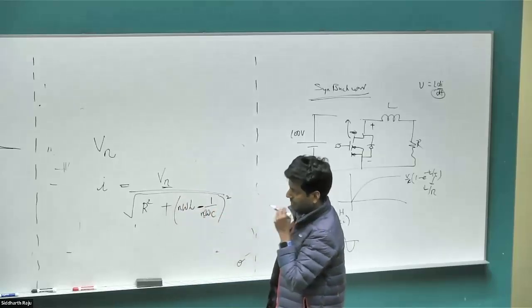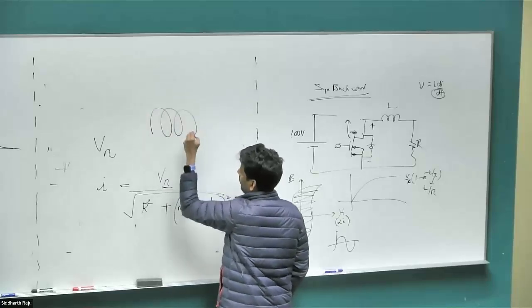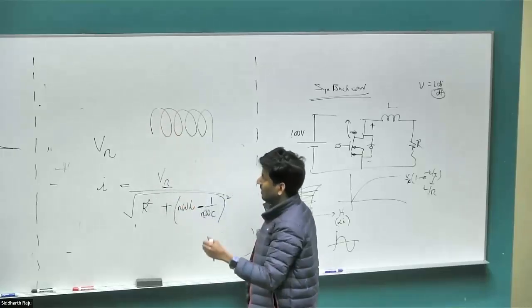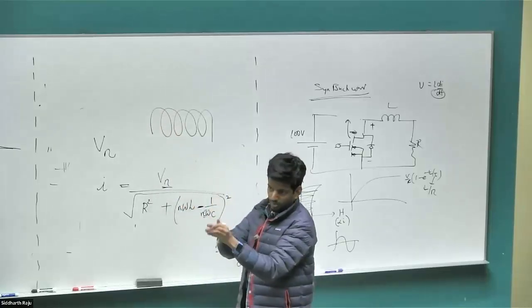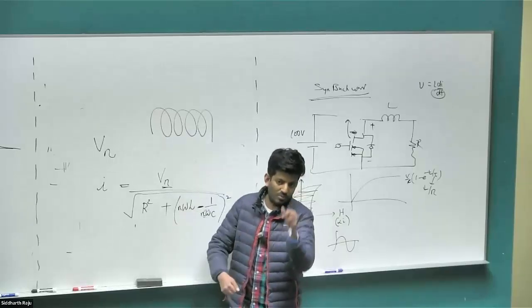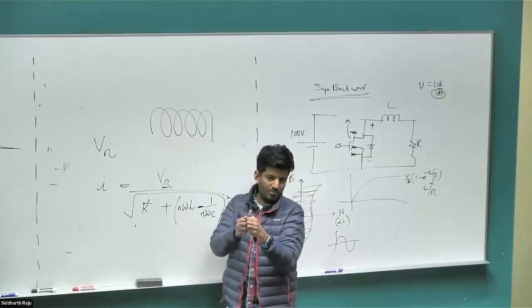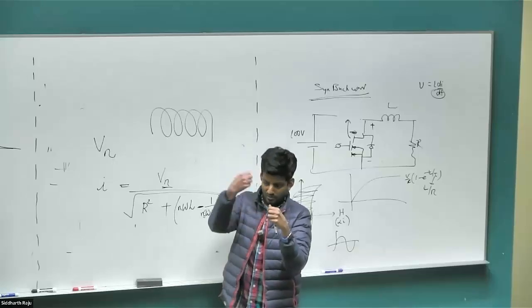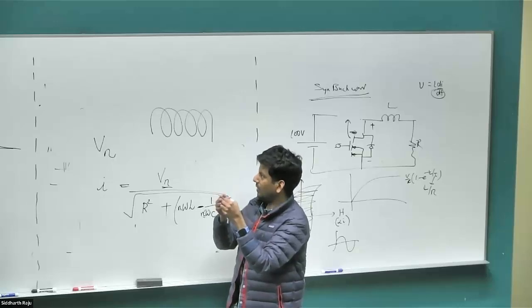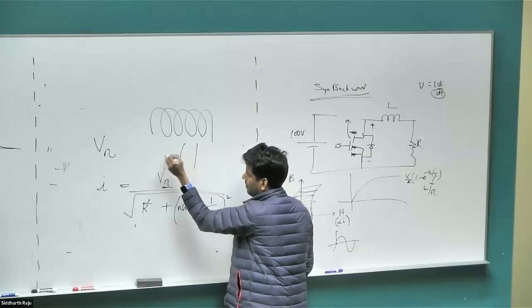This is a very big problem in power electronic networks, because anytime we wind an inductor on an iron core, or any core for that matter, we have one coil here and there, and we said that it needs to be jam-packed as close and tightly wound as possible. That is an advantage in one way, but a very big disadvantage in another, because you have created a winding and another winding right next to it. What you have created is a parallel plate capacitor. You have a metal coil here, a metal coil here, separated by some distance, by some varnish, which is a very good insulator.